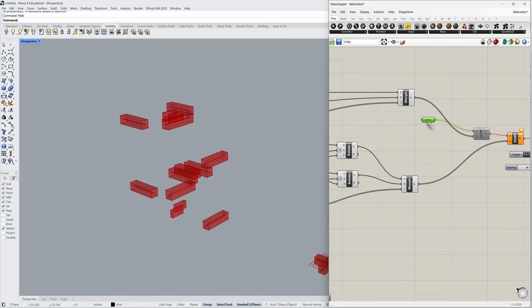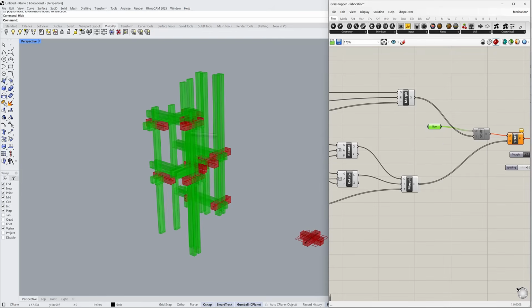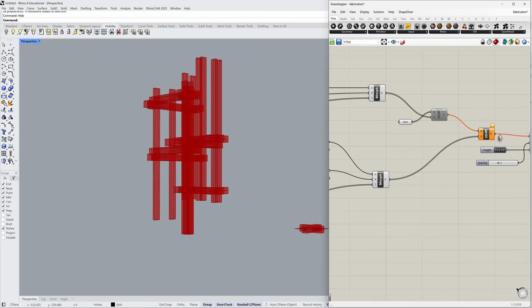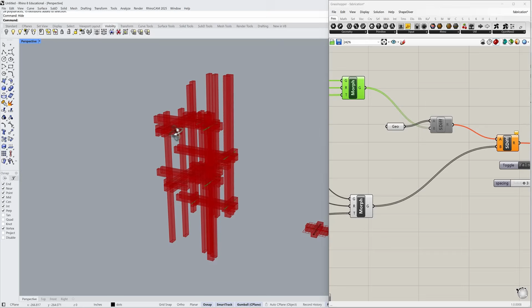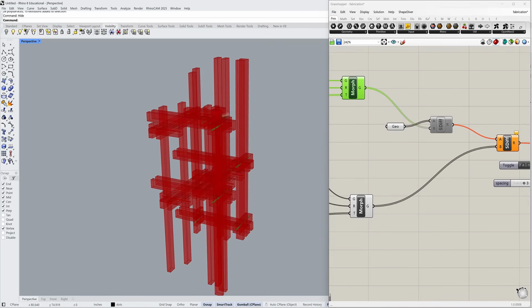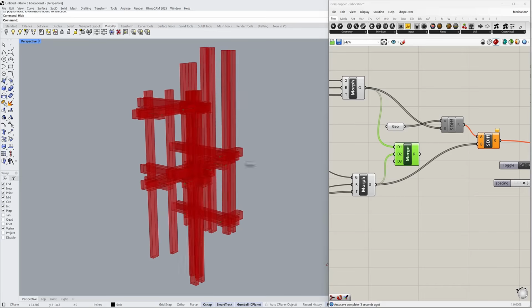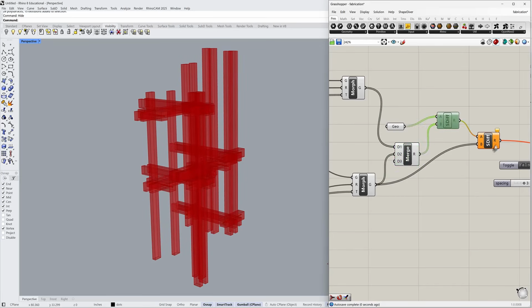And the next step is, after you have those cylinders placed, we can actually have all of our geometry fed in, and we can do a simple solid difference. And you might want to just sequence this. So you might want to first do a solid difference in this direction, or we can actually probably do it at the same time. So if I do, for instance, merge, put both of the cylinders inside one container and just do a solid difference.